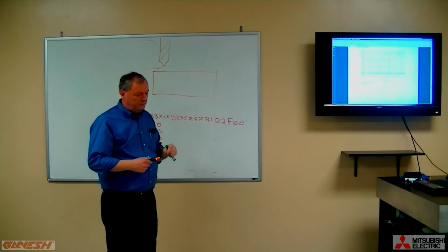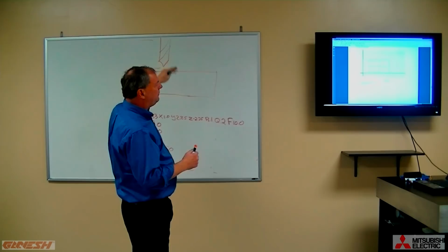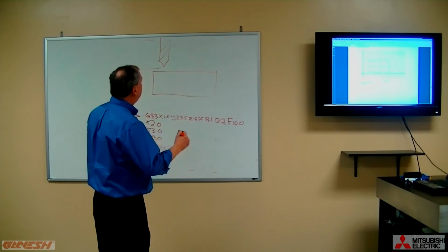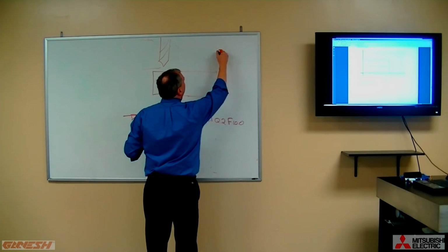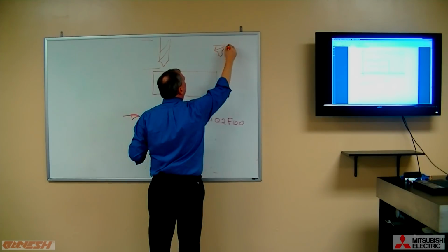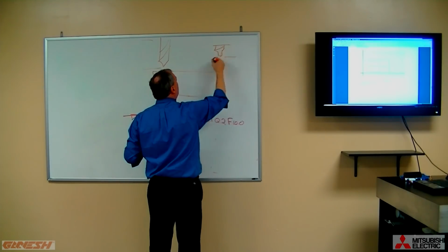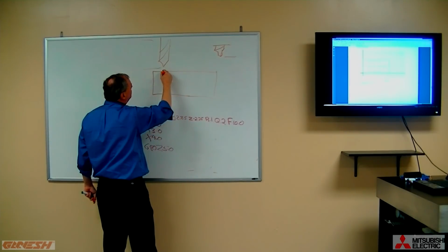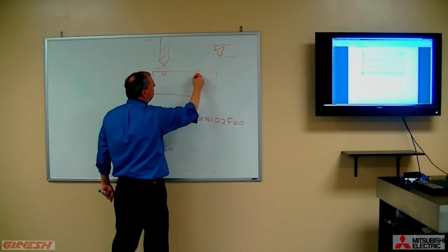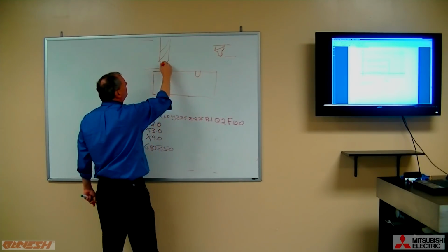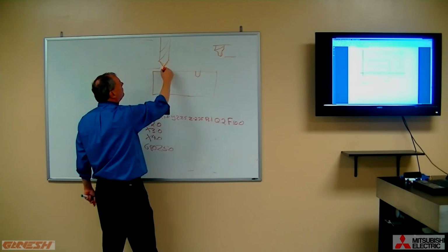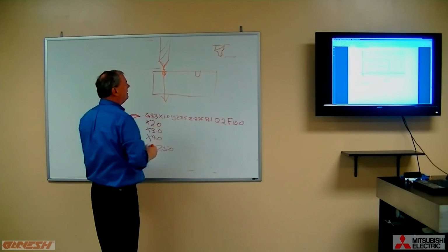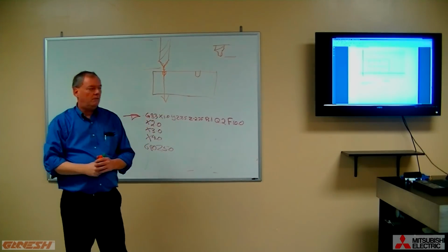So what we tend to do before we drill with a full-size drill, we come at it with a very short and stubby little drill that is really just a short little stub sticking out, and what it does is it makes a small starter hole for a full-size drill. So now you position the full-size drill over the spot drilled location, and the spot drilled hole lets this drill get a good start to make a finished hole. So you're going